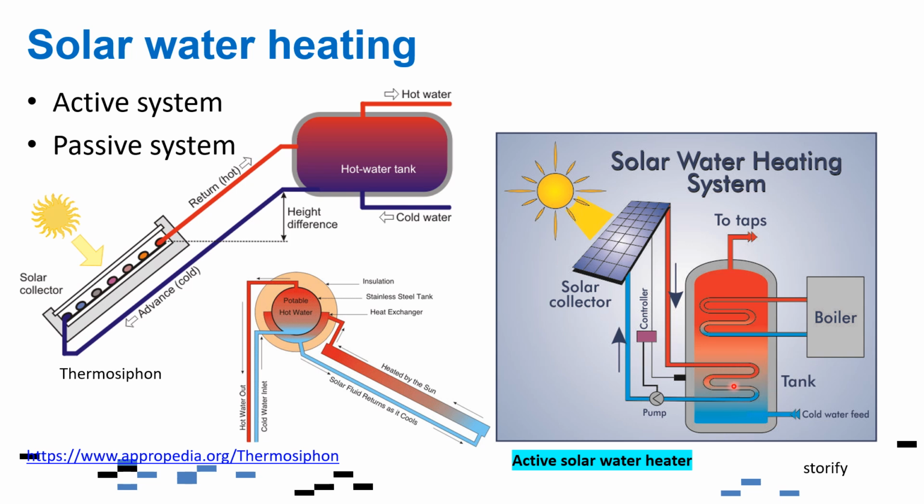After heat exchanging, it goes back towards the pump, as colder water now, and goes back again towards the solar collector. So this process just continues indefinitely, until such time that some of the fluid has to be replaced inside the pumping system. This is the form of an active solar water heating system. On the other side is the passive one.